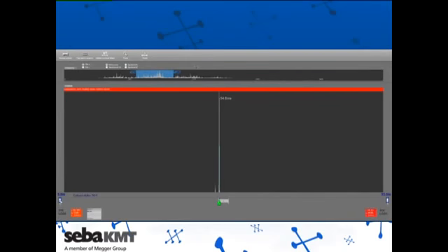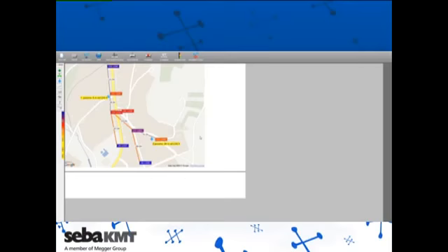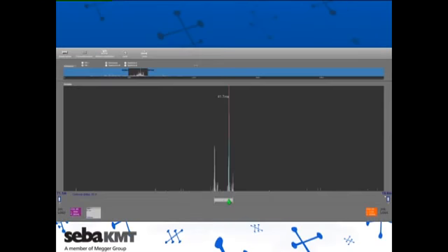Leak number 2 was surveyed between sensors 3 and 4. We also see a clear correlation result and a leak distance of 20 meters from sensor number 4. The surveyed leak locations were then verified and pinpointed using the pinpoint function.